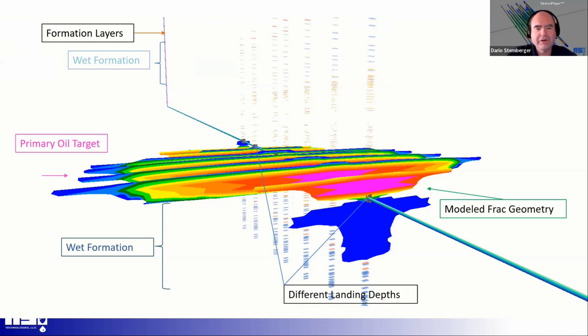You go to engineered completions, they can certainly lead to a lot longer times between stages, you're changing guns, you're changing a lot of things. Most field guys like one program, everything is the same, and you just repeat, and that's where you get your efficiencies. If you're fracking one well a year, 10 wells a year, I would definitely look at engineered completions.